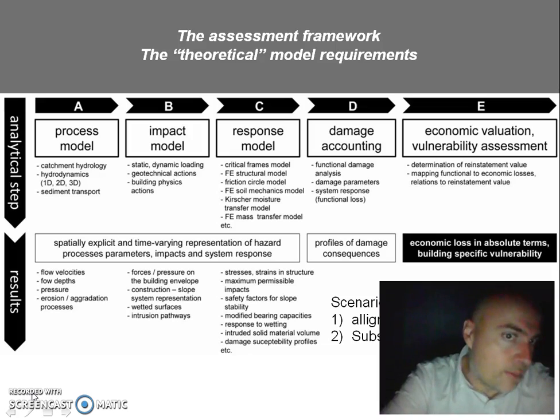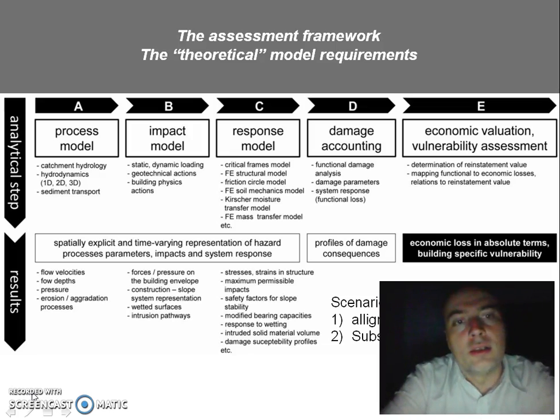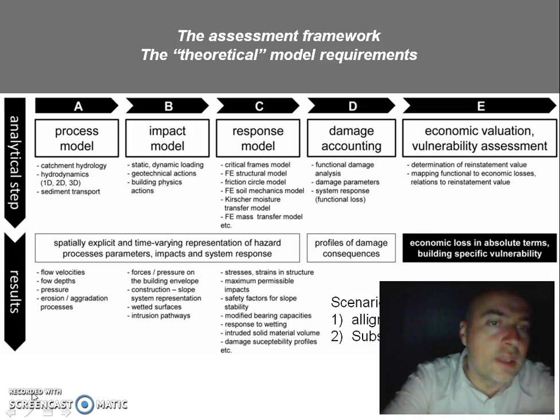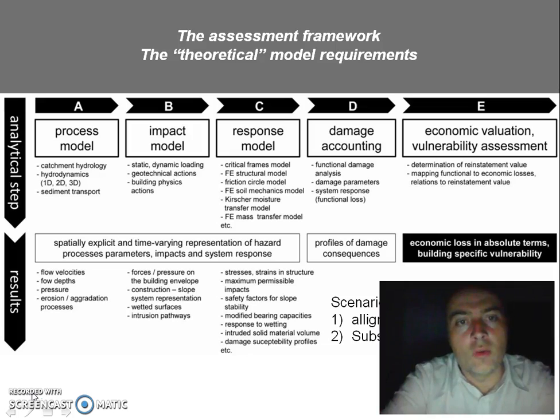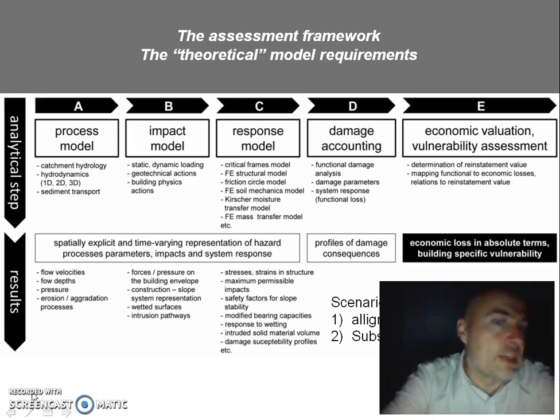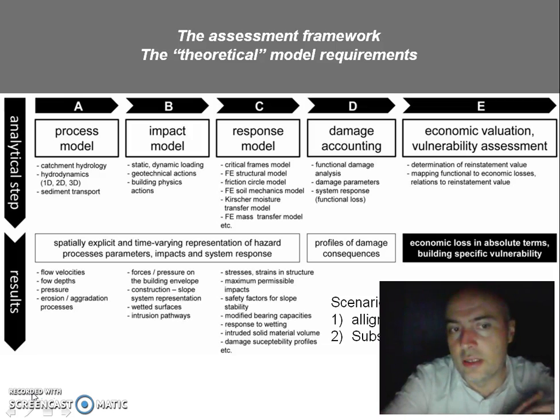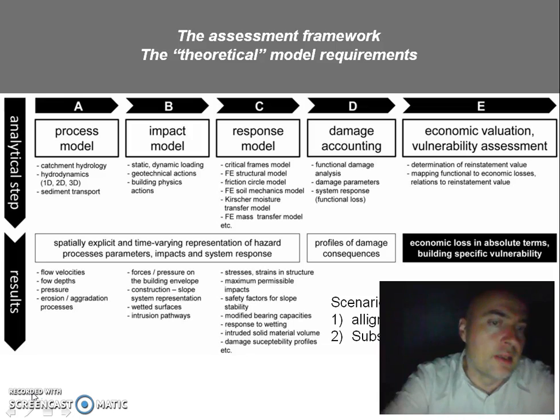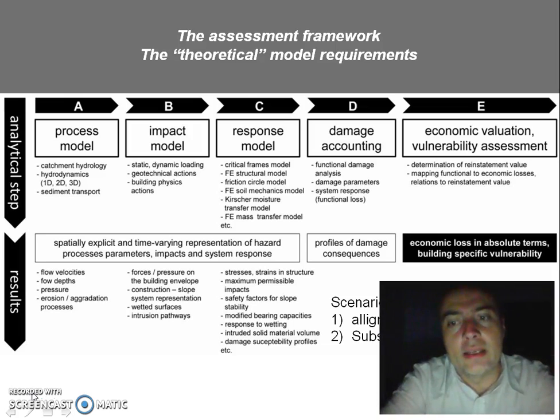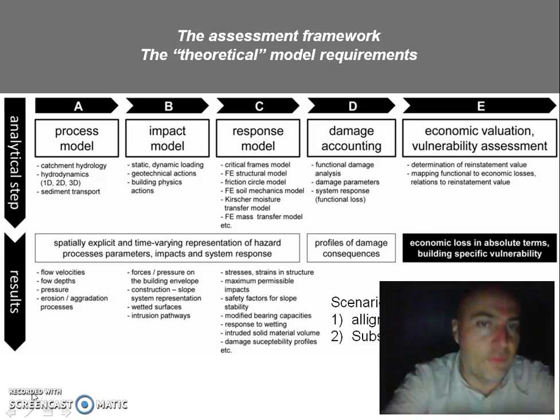We perform hydrodynamic modeling, either in a 1D, 2D, or 3D fashion. And this hydrodynamic modeling may also take into account sediment transport processes. Once we have the representation of the flow velocities, the flow depths, and the pressures, both in space and time, so we have several maps that represent the variability of these parameters in the computational domains and also throughout the event time, if you want.